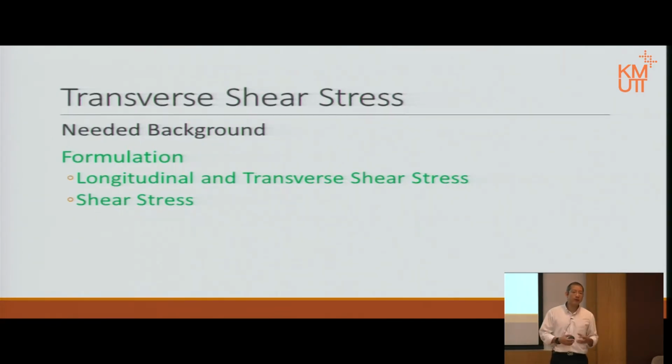And once we prove that part, then rather than calculating the transverse shear stress straight away, we actually calculate the longitudinal shear stress, which is equal to the transverse shear stress anyhow. And then we'll prove the expression for the shear stress. Again, transverse and longitudinal are the same. Therefore, calculating one, you know the other anyhow. Okay? And then, of course, as usual, we'll see some examples on how we calculate the shear stresses.